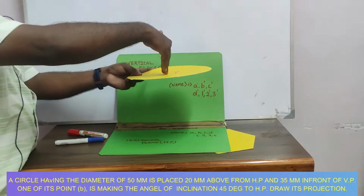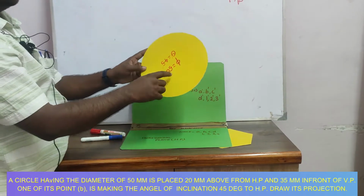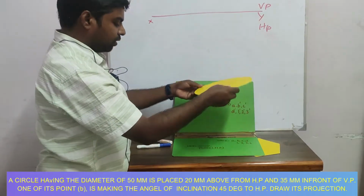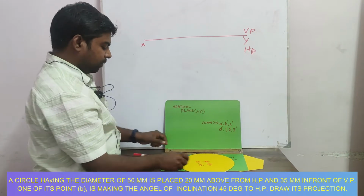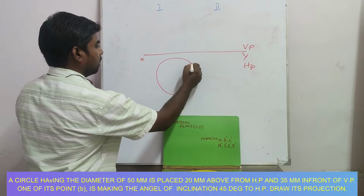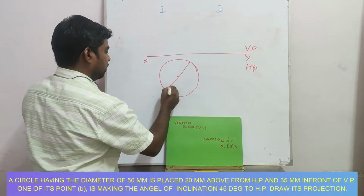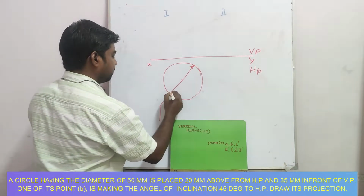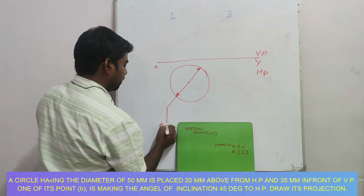So when you are seeing from the top view you will get a circular disc. When you are seeing from the front view it will be a single line which is equal to 50 mm diameter. So top view projections will fall on the horizontal plane. Okay, top view projection will fall on the horizontal plane. So we are going to make this circle first. Okay, this circle whose diameter is equal to, now we'll put some layout lines, close this, close this. So 50 mm.